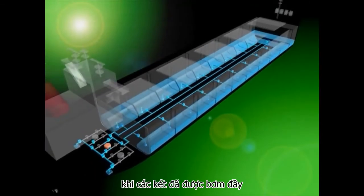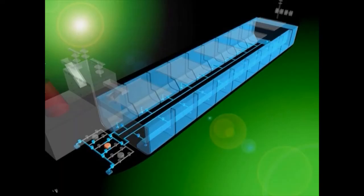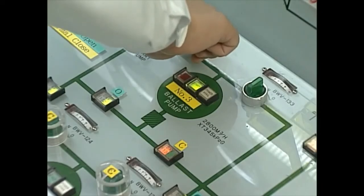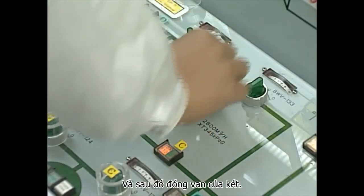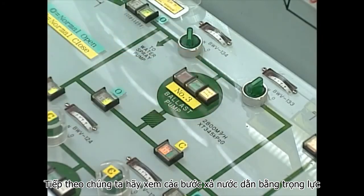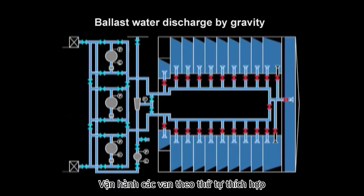Filling of all tanks has been completed. Stop the pumps by closing the ballast pump discharge valves and then close the tank's valves. Next, let's see the steps for ballast water discharge by gravity.